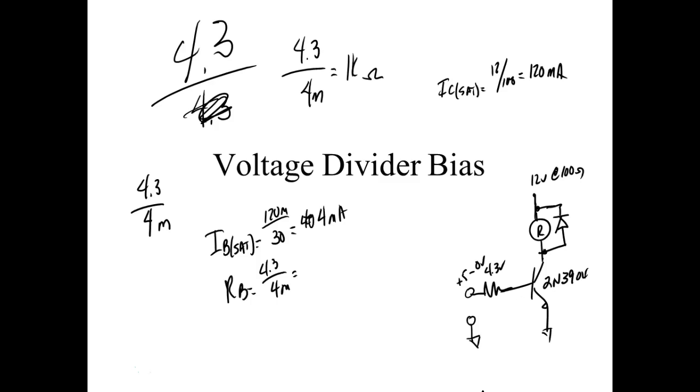As long as you have the required current and the required voltage, you could hook as many LEDs in series as you want, and every one of them would get the same current, which is pretty nice.